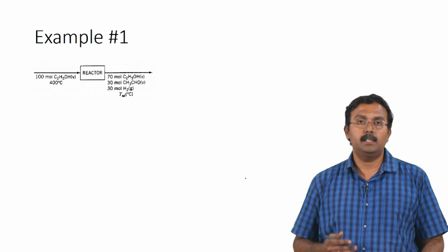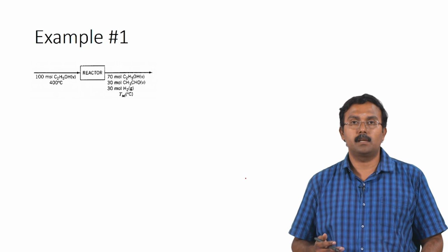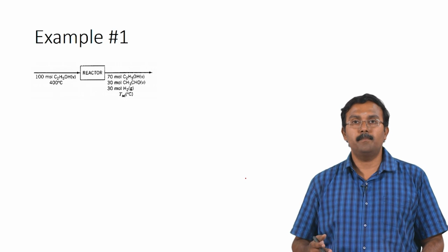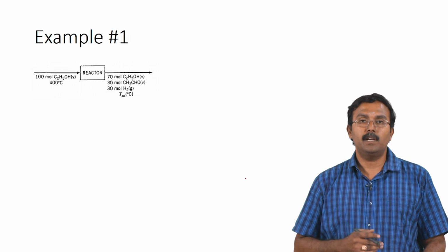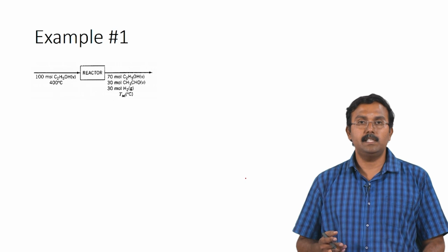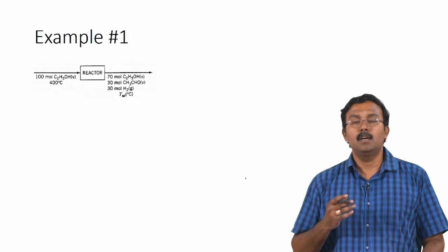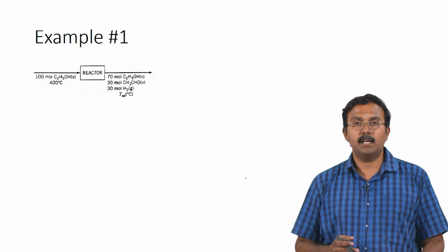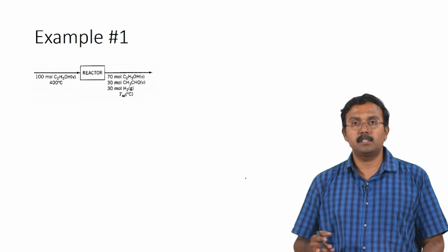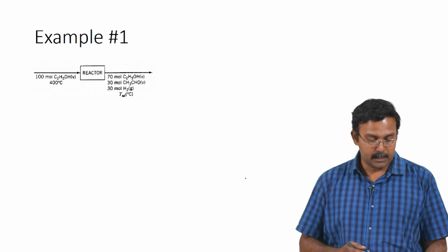Now that we have calculated the enthalpy for the inlet streams, we need to move on to calculate the enthalpy for the outlet streams. As you know, the outlet stream temperature is not known. So, we would have to use an integral from 25 degrees Celsius, which is the reference state, to the temperature of the outlet, which we have assumed to be T degrees Celsius. We will perform this calculation using the Cp values for ethanol vapor, acetaldehyde vapor and hydrogen gas, and we will get polynomials in temperature, which will be used for solving for the value of T. So, let us try and do that.